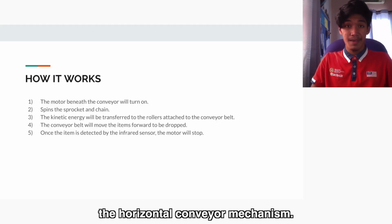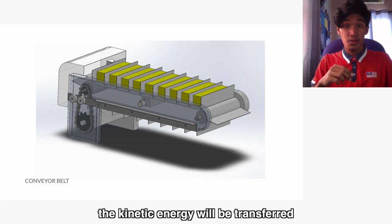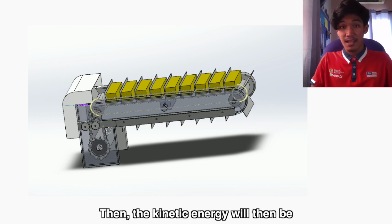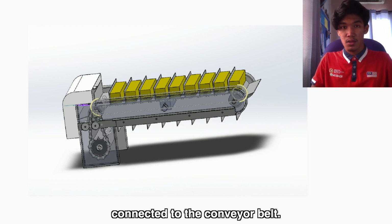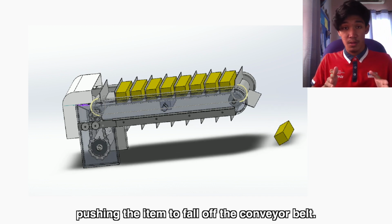Let us look deeper into the horizontal conveyor mechanism. The motor beneath the conveyor powers and turns the conveyor belt. As the motor is spinning, the kinetic energy will be transferred to a sprocket and chain structure by spinning it. Then, the kinetic energy will be transferred to the roller connected to the conveyor belt. Therefore, the motion generated will move the conveyor belt forward, pushing the item to fall off the conveyor belt.